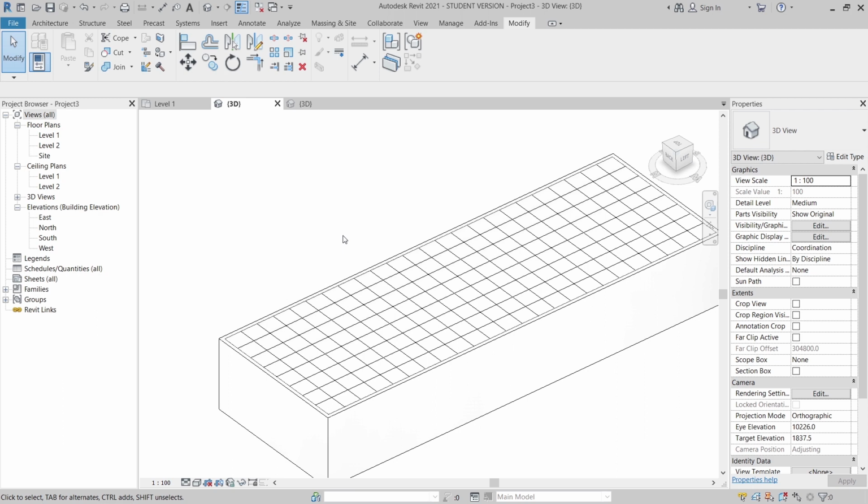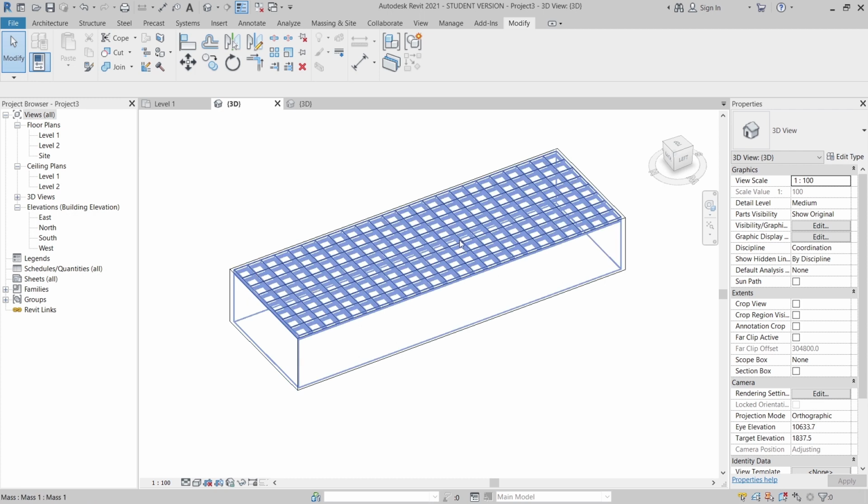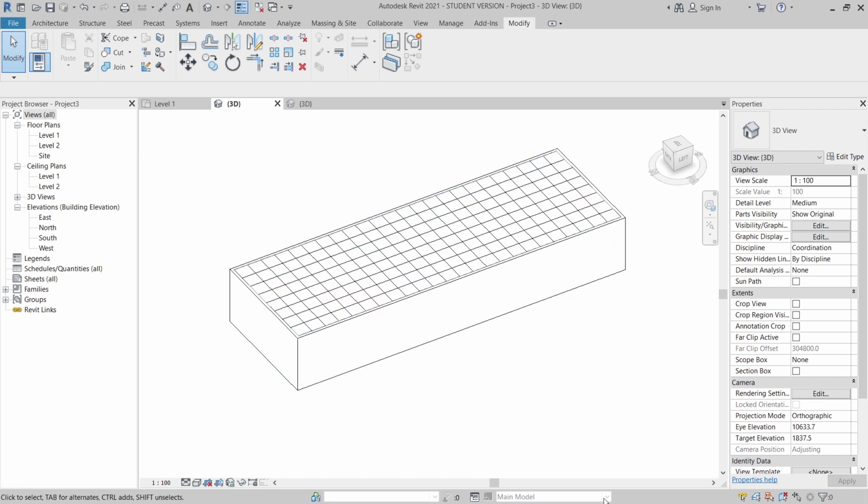So now I want to place light. How to place that? Basically, if you are directly to place light on our mesh here, we could not place that because we need our ceiling to host that. So how can you show that? Let me open back my light first, and you can download lighting link on description. You can download from that. And of course you can go to Revit City and search from that because I got download from there.